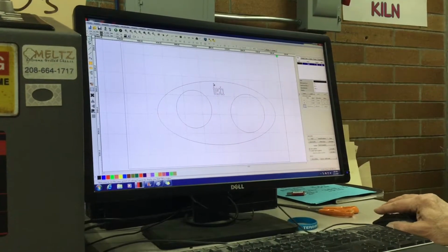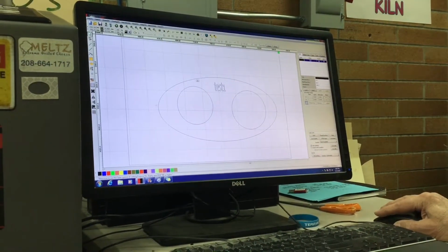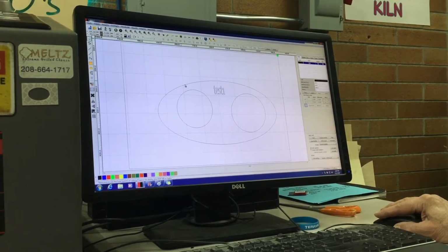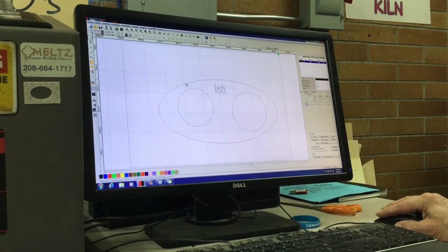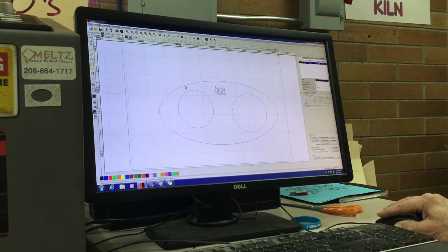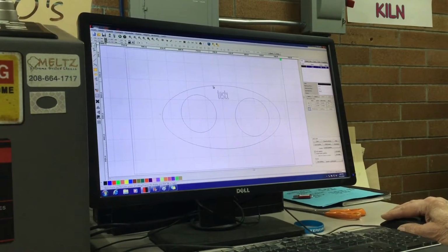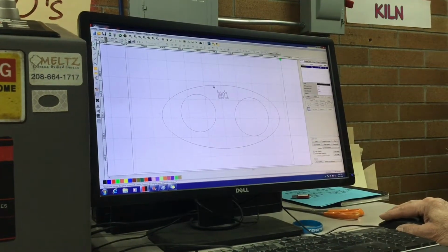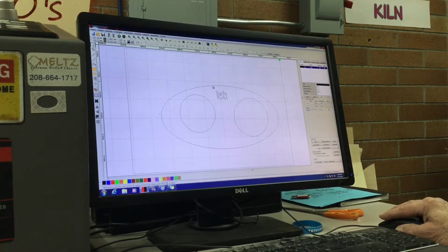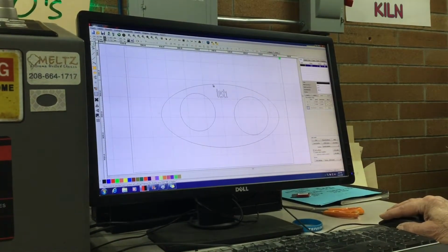You can just follow a single line, and depending on how you set the power and speed, that could either just be marking that line like a wood burn, or it could be cutting all the way through the material. If you just want to mark it, you move pretty quickly and run a low power. If you want to cut through, you'd move more slowly and run a higher power on the laser. So the way that you would do that,